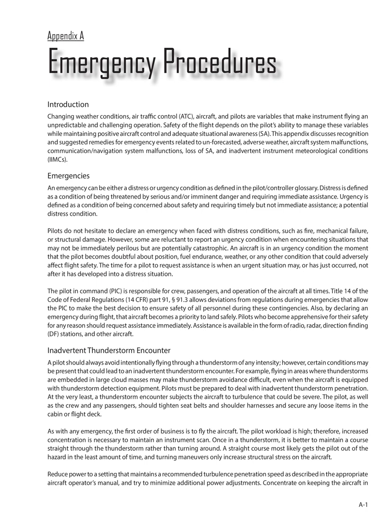Emergencies. An emergency can be either a distress or urgency condition as defined in the pilot/controller glossary. Distress is defined as a condition of being threatened by serious and/or imminent danger and requiring immediate assistance. Urgency is defined as a condition of being concerned about safety and requiring timely but not immediate assistance, a potential distress condition. Pilots do not hesitate to declare an emergency when faced with distress conditions, such as fire, mechanical failure, or structural damage. However, some are reluctant to report an urgency condition when encountering situations that may not be immediately perilous but are potentially catastrophic.